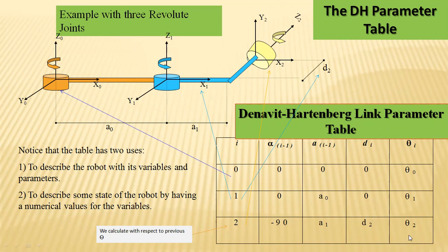So simultaneously, in this way, based upon these 4 different parameters, there is A, D, shifting distance, theta, there is rotation, and alpha, there is revolution or orientation, shifting of its angle, or shifting of the entire coordinate frames also will be considered depending upon this alpha value only, right? So that is the calculation that has to be commenced based on these DH parameters on each and every joint, and has to analyze the end effector position.